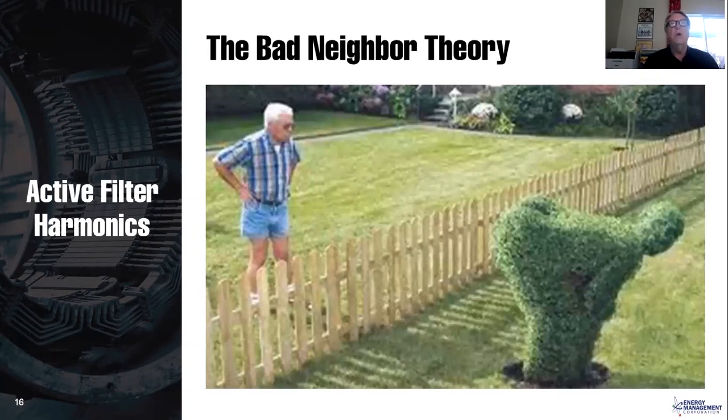So when you pollute that system, you can do one of two things. You can either clean up the harmonics, or you can have equipment on that system that's capable of withstanding those harmonics. So if you're having lots of problems, let's say with your communication system, well, maybe you can put a device on there that's going to filter those harmonics out just for the communications devices.